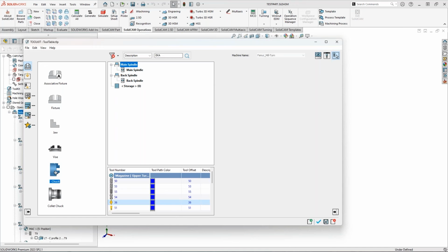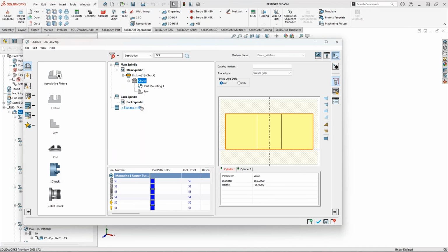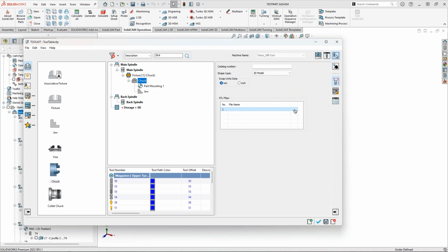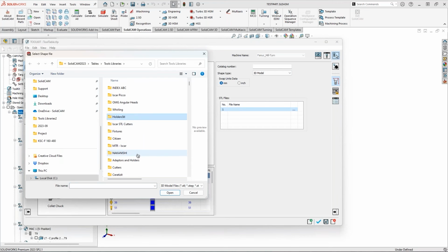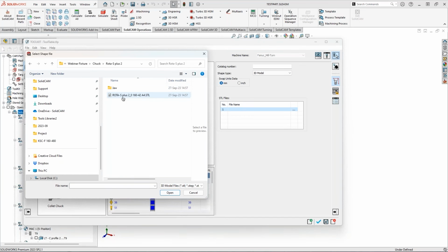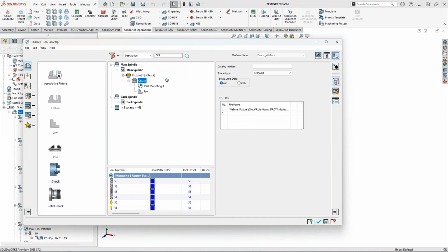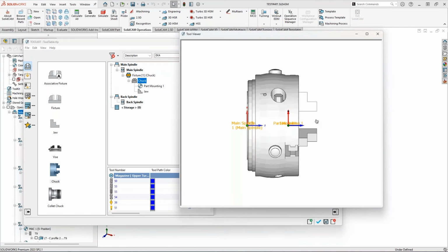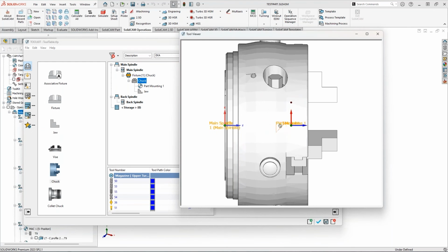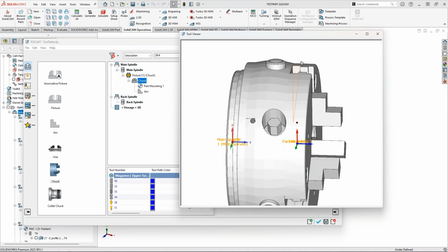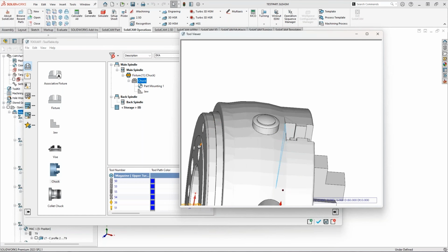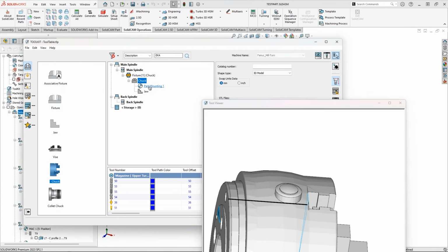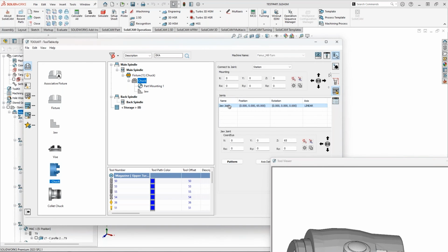and I'm going to take a chuck. The template is there, and I'm going just to select 3D model and pick up these STLs. So webinar chuck, take it. Of course, you can save this one over here. What we have here is that now I need to care about the jaw position, and the jaw position is actually on this surface over here. So you can just take the simple measurement, which is exactly 16. So my part mounting, just move it here, and my jaw joint, move it to 60, this point over here.